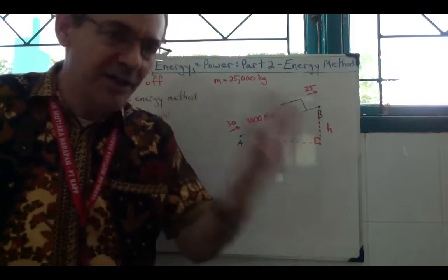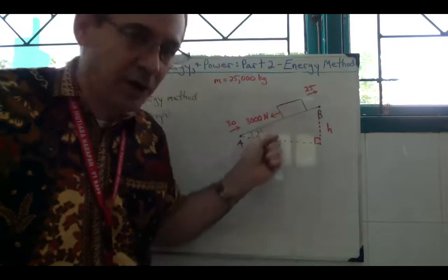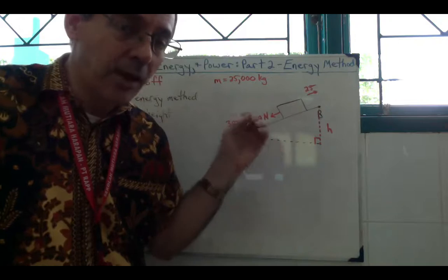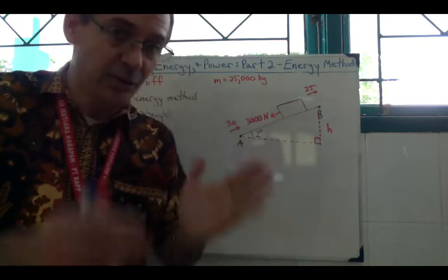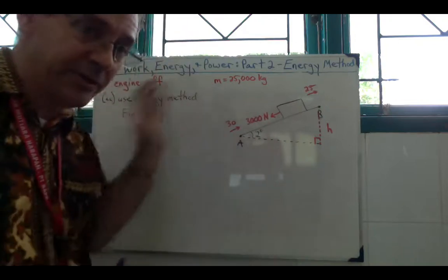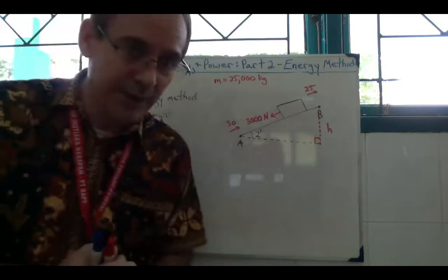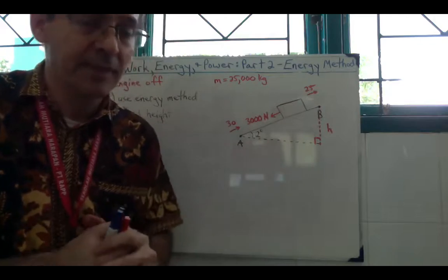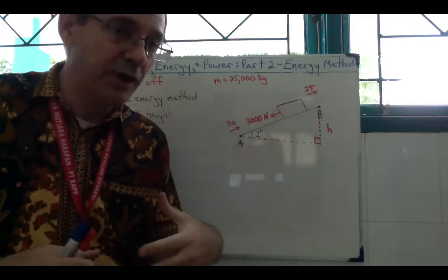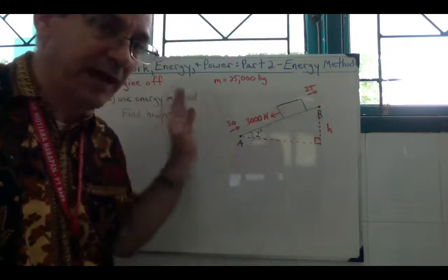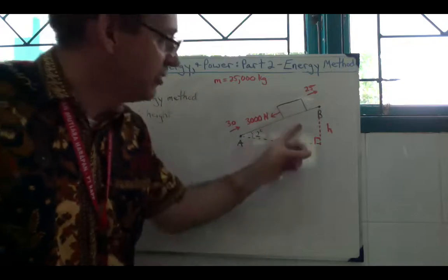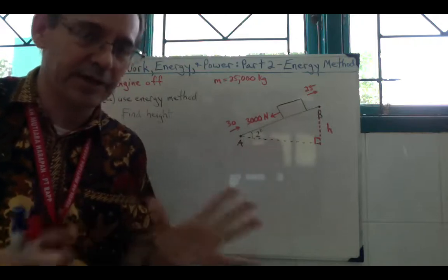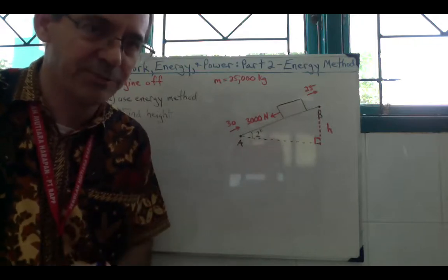So I use that to help me remember when to resolve the weight and gravity and when not to. If you're doing PE, the energy method, you don't need to watch your weight. You don't need to resolve the weight with gravity. If you are not doing PE, if you're not doing the energy method, then you need to resolve parallel to your inclined plane. That's what I use to help me. I hope it helps you remember.